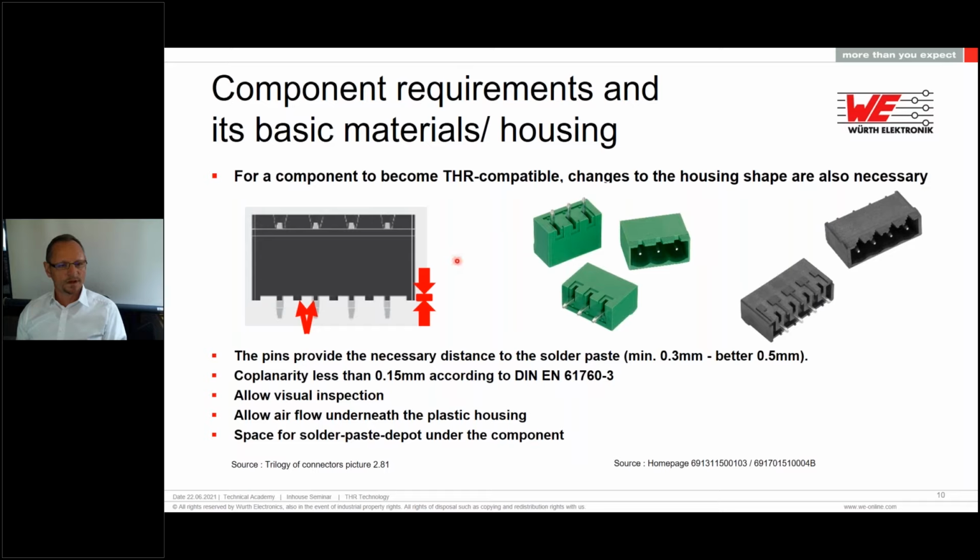So what are they for? Of course, afterwards you can have visual inspection. You can look under it. The AOI will be difficult if the camera is on top, but if you look from a side view or from an angle, you can look pretty well under the component to inspect how your solder joint looks.